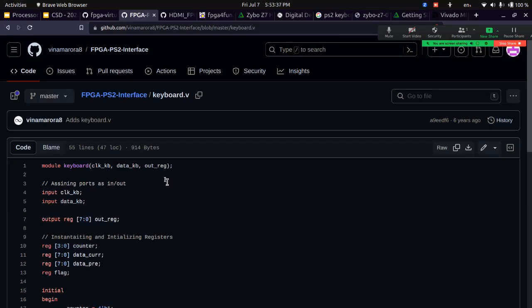You assign a special memory address which is accessible. When the user asks for this particular memory location, you assign this memory address to be something out of the total address space. The address space is 240 KB, right? You assign something out of the scope, or you assign a specific address for this particular 8-bit register. Whenever the address is fetched, you keep checking, like we divided the memory into 3 parts, right? So whenever the user asks for this particular address, you will be checking whether it's a display memory address or a ROM address or RAM address.